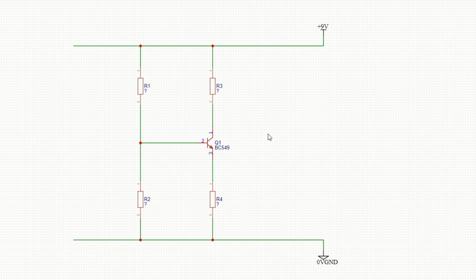So if your next stage has an input impedance of 100k, the highest possible value you should use for that is 10k, and preferably lower, say 4.7k or 2.2k. The higher the ratio, the less effect the loading of the next stage has on this stage. But obviously you can't go too far. You can't start using 10 ohm resistors in the collector on a small single transistor and expect it to do anything practical.